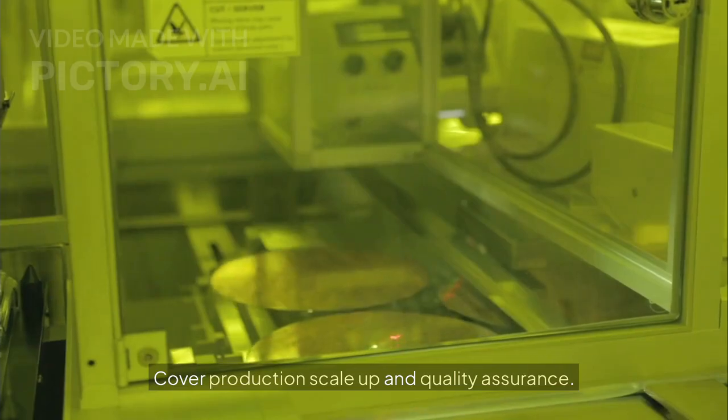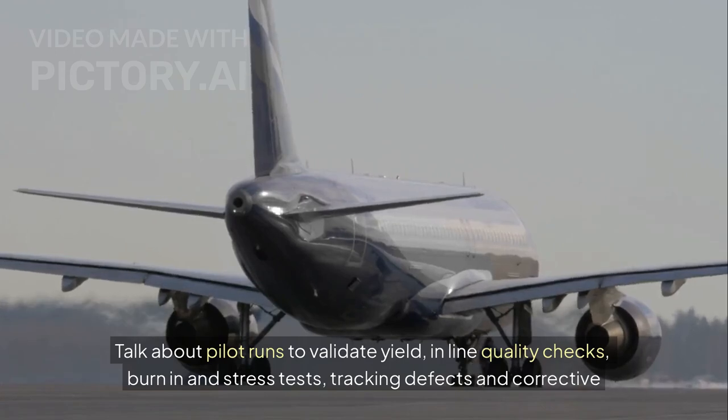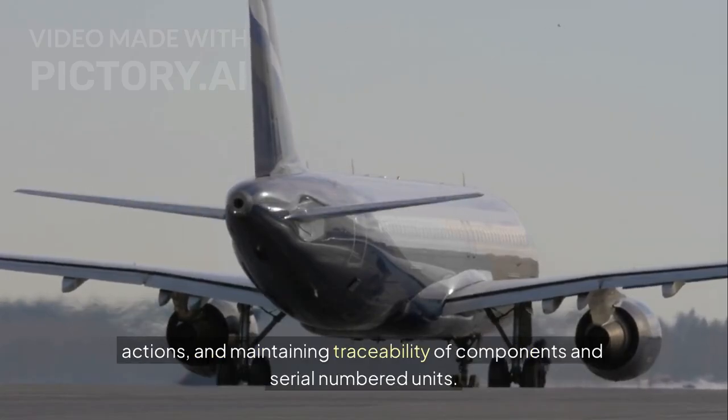Cover production scale-up and quality assurance. Talk about pilot runs to validate yield, inline quality checks, burn-in and stress tests, tracking defects and corrective actions, and maintaining traceability of components and serial numbered units.